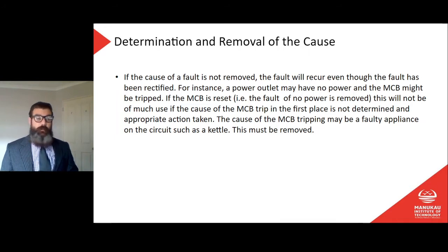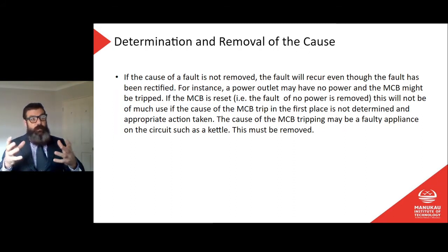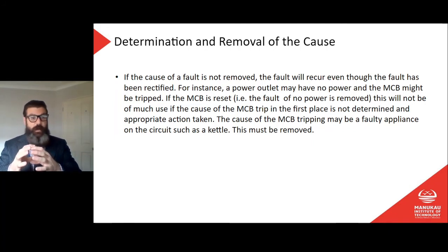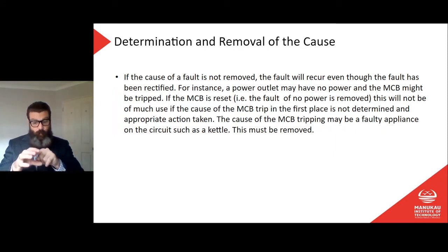But sometimes, especially if you're doing something a little bit more complicated, I mean, we're talking about a context of a domestic installation, where if you're fault finding inside a machine that has complicated parts, switches and circuit boards and electronics in there, you may reduce the fault down to one circuit board, but you're not going to fault find that circuit board. You just pull that out, put another one in.